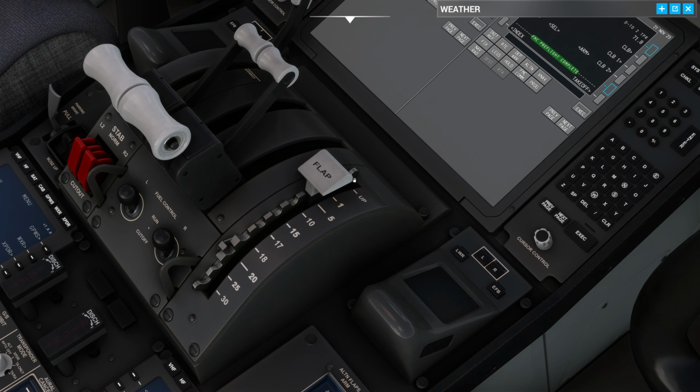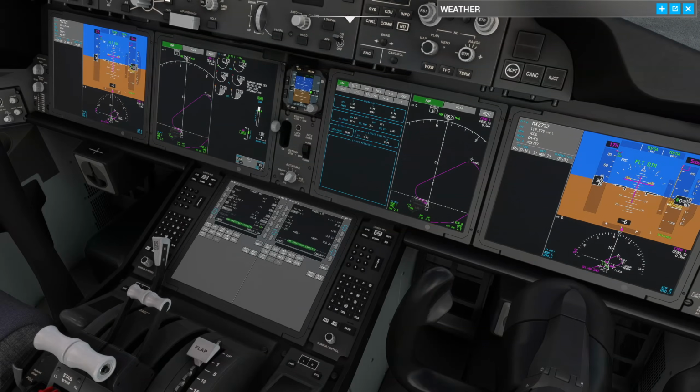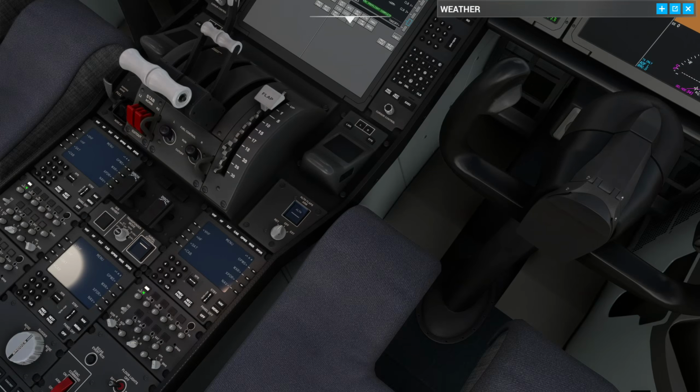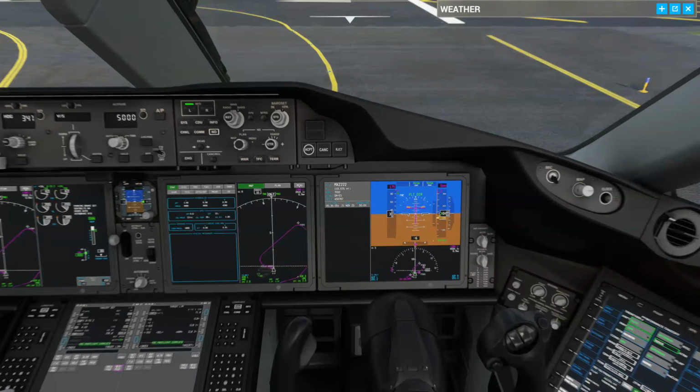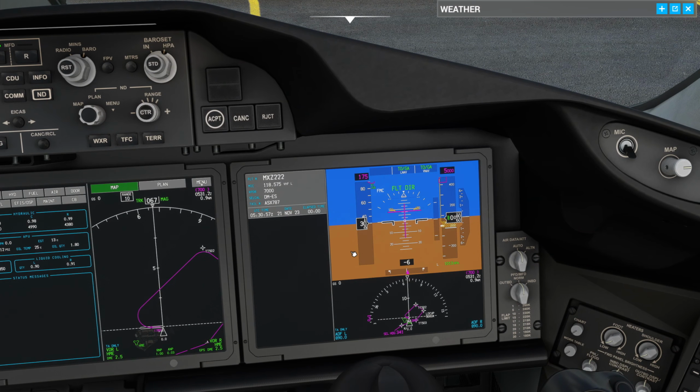So what the 787 likes to do is take off flap 5, and like I say, 9 times out of 10, that's what you're going to do. Something to remember though, if you don't take off at flap 5, there's a slightly different change to the schedule. And what do I mean by schedule? Well, once we take off, we're going to then bring in the flaps, and if we were at 20, 18, 17 or 15 or 10, any of those settings, we go from those straight to 5. So if you're 18, it goes 18 to 5, and then 5 to 1, and then 1 to up. If you take off at flap 5, you go 5 to 1 to up. So basically, any setting to 5 to 1 to up is how you retract the flaps in that order. But we'll talk about what you're going to be looking for on the speed tape.